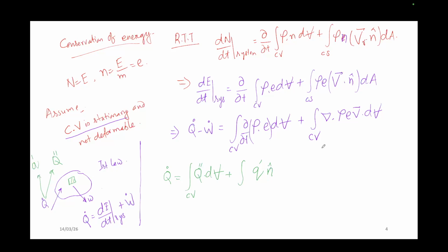Okay. So this is the heat flux. Because of this Q there is heat generation here, and the heat is moving out, which is Q dash. For understanding purposes, I can represent it with a minus. This is because of the sign convention: in the first law of thermodynamics, we take heat entering the system as positive, so heat going out is considered negative. You can choose the inverse configuration; I am talking about the sign convention.